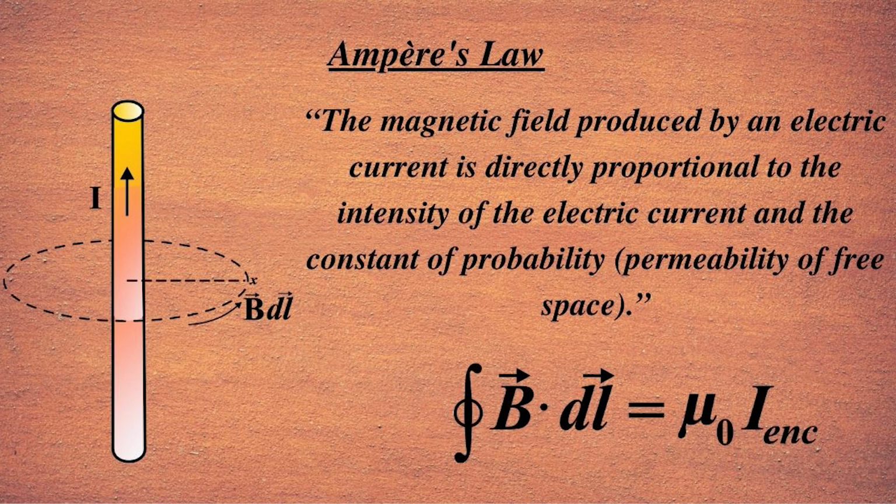So, let us see the magnetic circuits in detail. We see that current in a coil of wire wrapped around a core produces a magnetic flux in the core. This we can say is analogous to a voltage in an electric circuit producing a current flow. It is possible to define a magnetic circuit whose behavior is governed by equations analogous to those for an electric circuit. The magnetic circuit model is often used in the design of electric machines and transformers to simplify the complex design process.